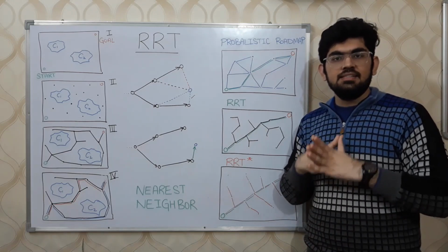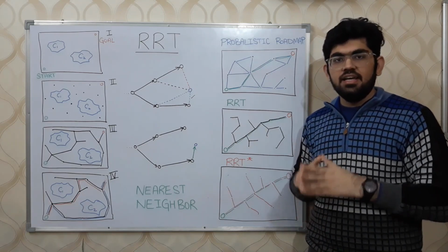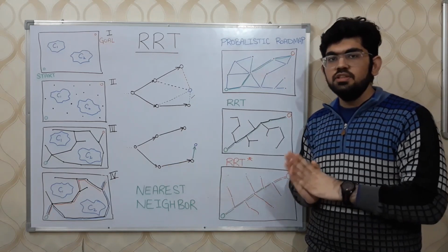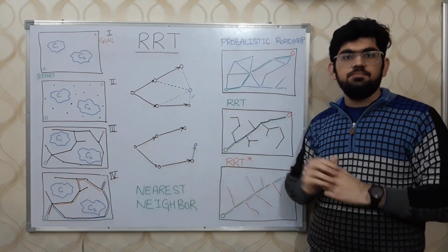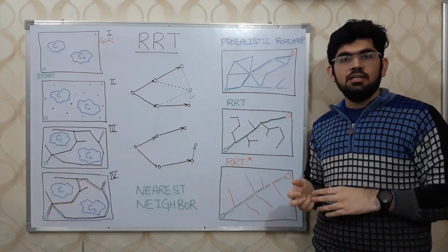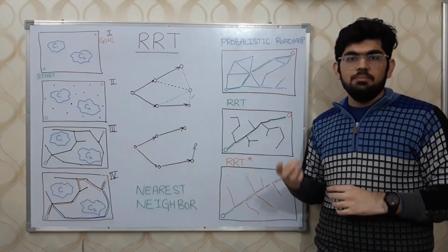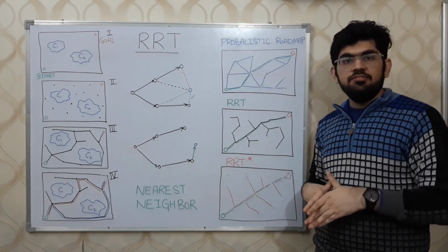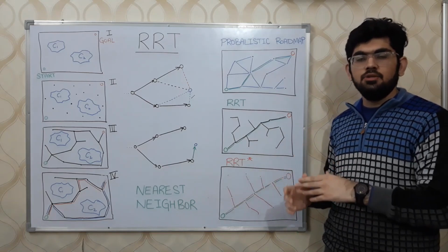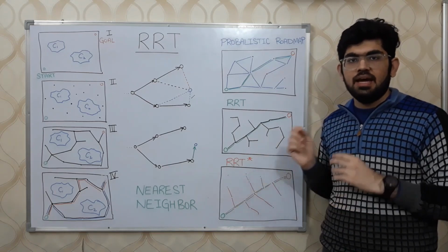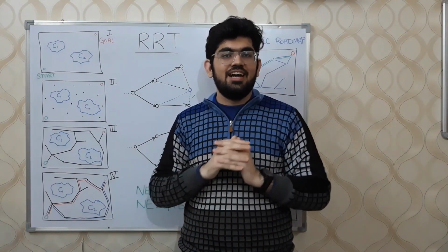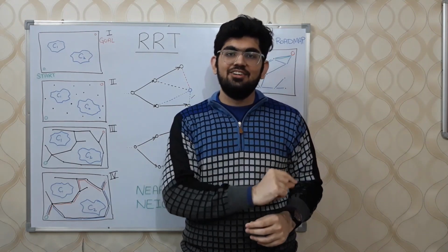If the distance is less, then we rewire a new path from this newly sampled node and remove the previous edge. These two modifications help the simple RRT algorithm to give better optimal paths. These modifications result in a rather straight form of tree compared to the vanilla RRT algorithm, as we can see over here. Alright, so this is it that we had to discuss for the RRT algorithm.